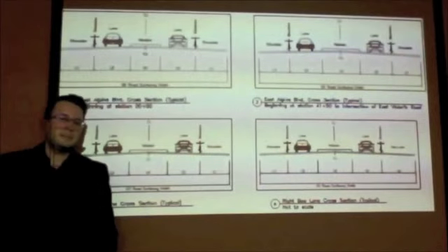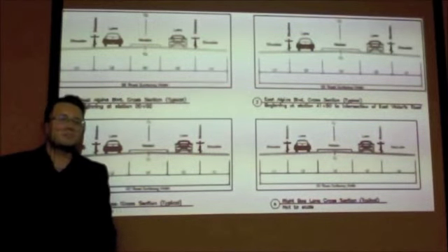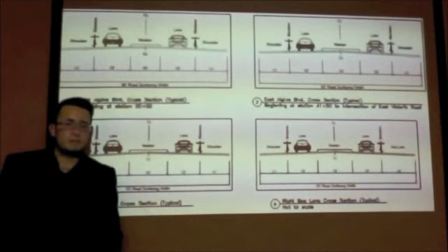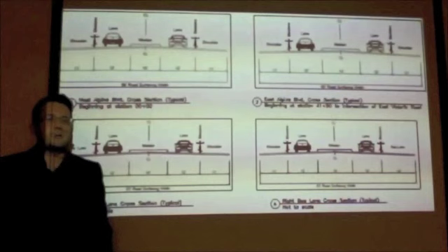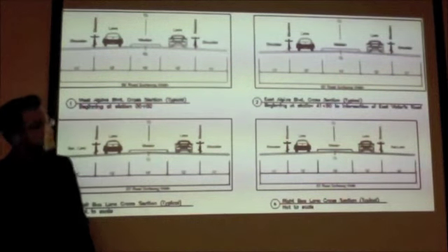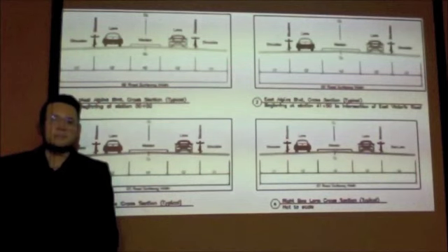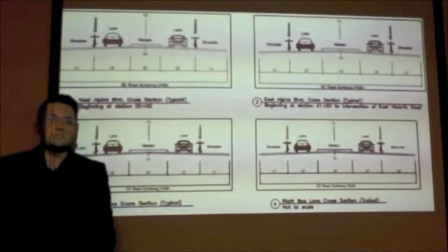The purpose of this road design study is to improve the 2-mile stretch of Alpine Boulevard from Tavern Road to East Victoria Drive, such that it meets current standards while maintaining the current natural setting. Since one of the criteria was to keep the rural setting, the current number of lanes had to be maintained. The road classification chosen is a light collector with raised median 2.2A to abide by the lane criteria and the County of San Diego public road standards.